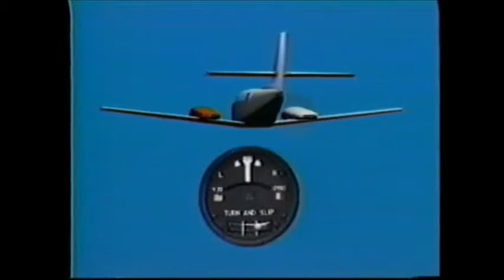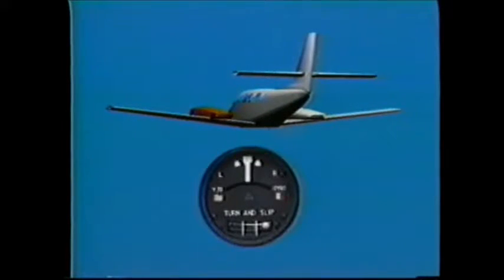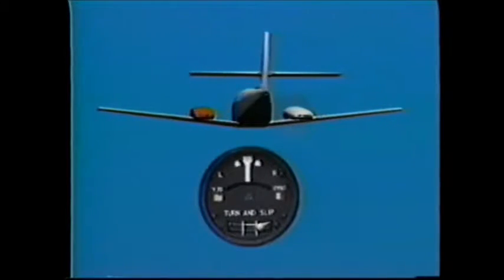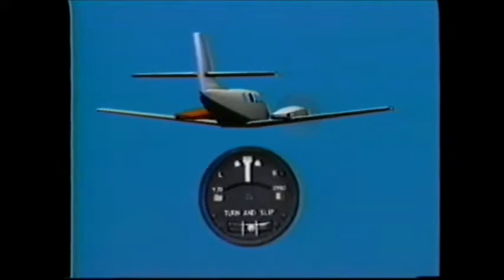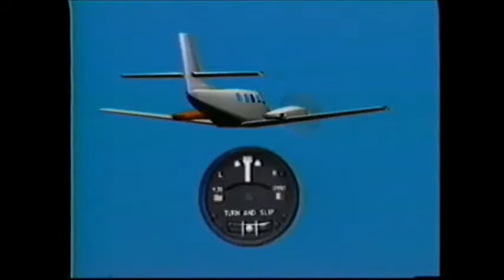The yaw of an engine failure causes the ball to move toward the operating engine. The amount of rudder pressure required to center the ball actually produces a side slip toward the inoperative engine. Flight tests have shown that this configuration may increase VMC as much as 20 knots and may reduce climb performance by 300 feet per minute in some airplanes.